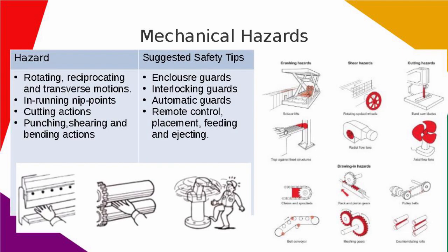Mechanical hazards. Hazard: rotating, reciprocating and transverse motions, in-running nip points, cutting actions, punching, shearing and bending actions. Suggested safety tips: enclosure guards, interlocking guards, automatic guards, remote control, placement, feeding and ejecting.